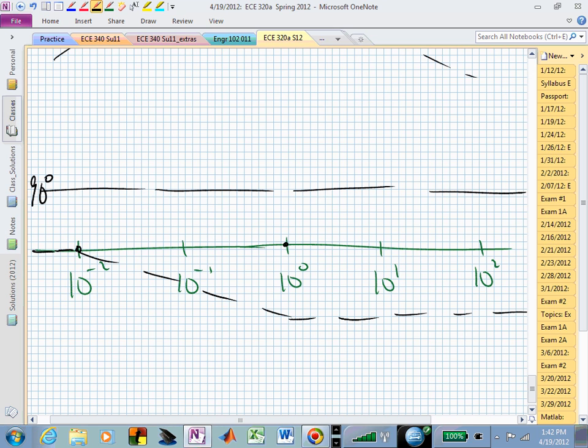The pole at 10 kicks in at the same place where the other one kicks out, and it turns off a decade beyond that, and so it will now be right there. Is that making sense? Now all we have to do is add them up on these vertical lines at each frequency, because these angles add and subtract because they're products in the transfer function. Doing such, we start at 90 degrees until we reach 0.01, and then we're sloping down.